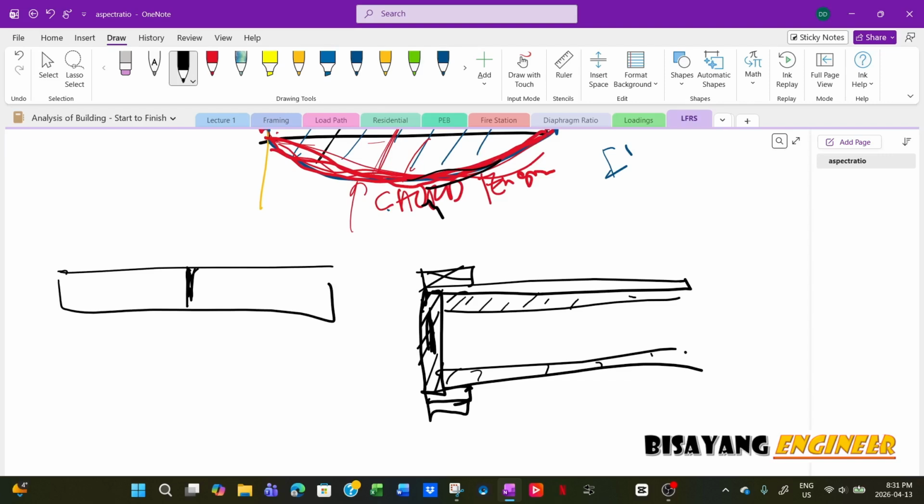I mean, if it's engineered wood, yes, you can go up to 40 feet without a cut, but for dimension lumber, I think in hardware stores you can get up to 12 feet, but if you go directly to the sawmill, you can go up to 20 feet, sometimes 24.